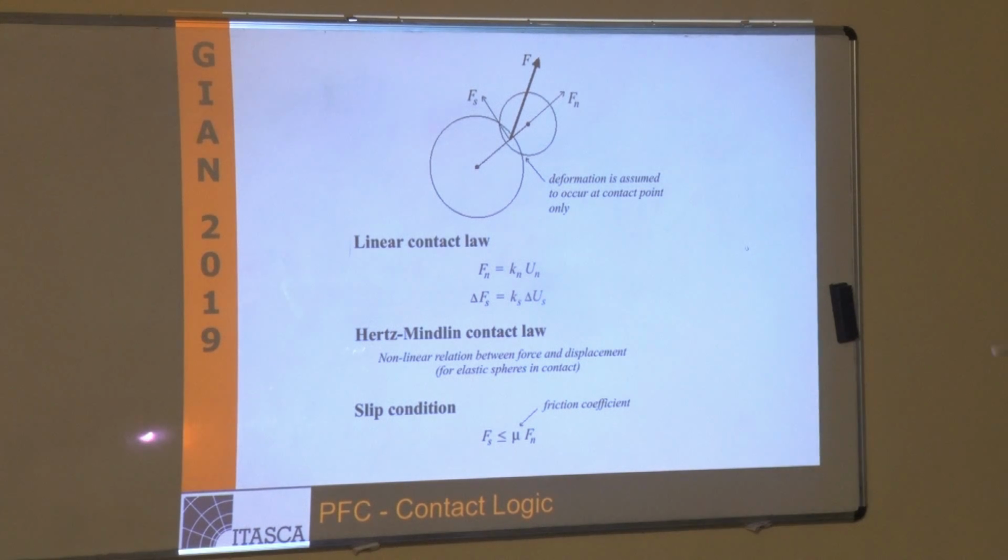So that means that you can use Hertz contact at the point, and then you need to start adding more and more constraints to reproduce the shear behavior, the slip condition, the contact, and so on and so forth. So, great idea, but very difficult to calibrate because the parameters are micromechanical parameters, which are very difficult to tie to properties that you measure in the lab.